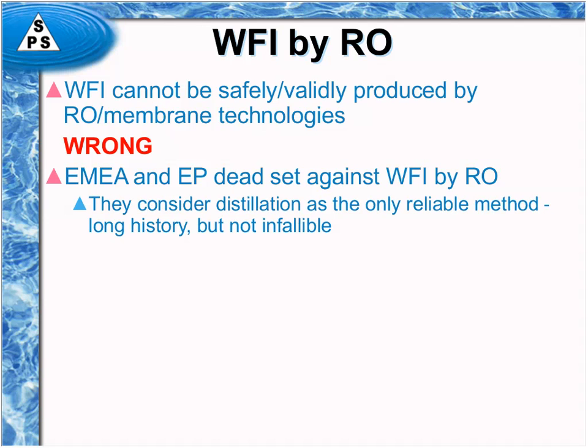They consider distillation to be the only reliable method, and it's got a long history of reliability, but it is not infallible. I have had many consulting projects, more than you can count on one hand, of situations where stills have not been able to protect against the carryover of endotoxin, which it's supposed to be an absolute barrier for.